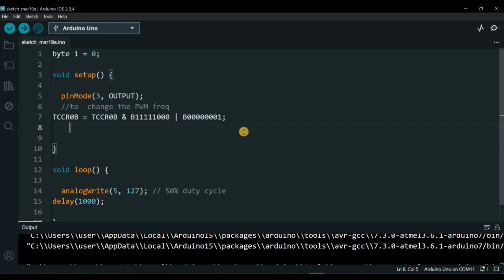Okay guys, so now we will start to develop the code for the potentiometer, the bonus code where we use the potentiometer to control the V out. Or actually control the PWM, which after we filter it out will be our DC V out. So now we will use the same code that we used previously, and we will add our new potentiometer so we can control this number, which is the duty cycle.